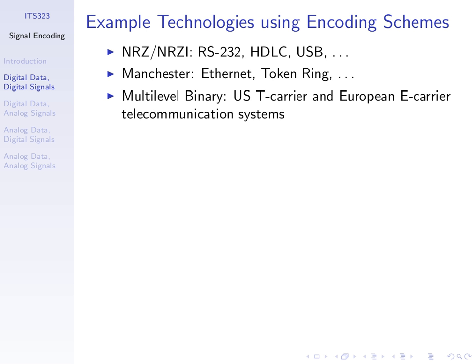Some of these others, which we just mentioned, like HDB3, are used in some long-distance wide area network links, which we haven't mentioned yet. So these are used in practice today for providing the conversion of digital data into a digital signal. It's not always this simple case of bit 0, one level, bit 1, another level. There are alternatives.